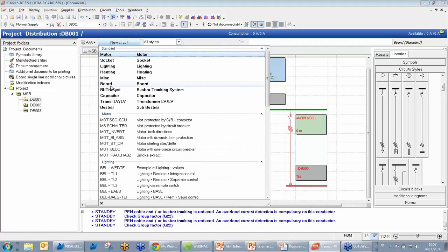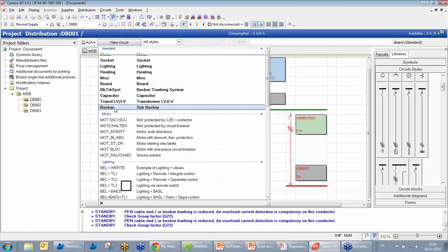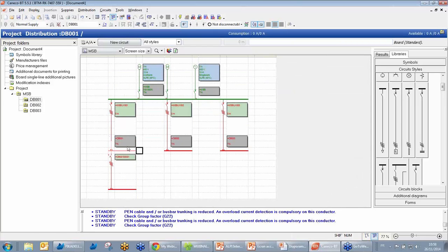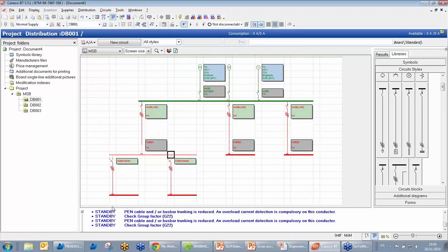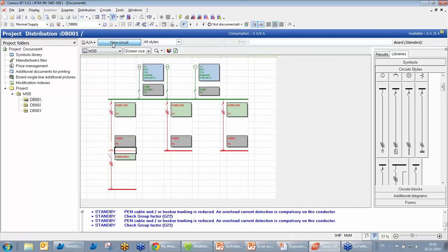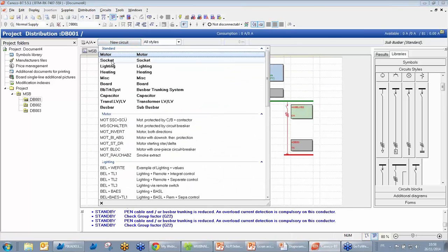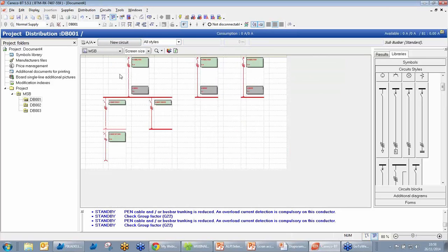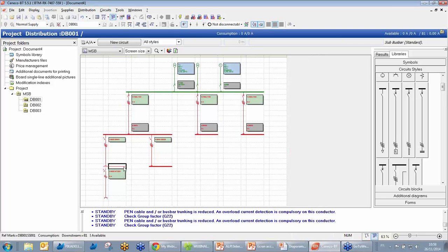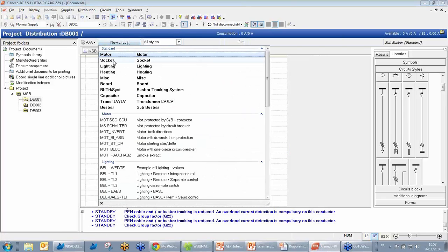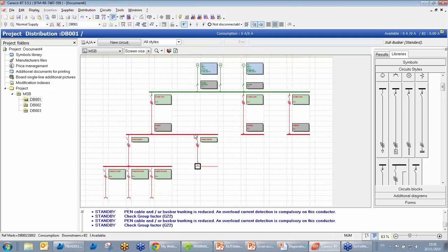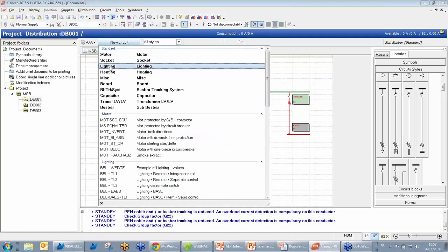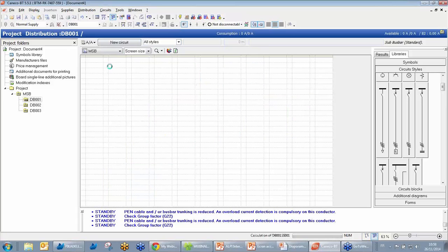Okay, then I can create some bus bar for the first one. Create another one. Create 2 bus bar. On the first one, I want something like for a building, an administrative building. I will create some sockets. Open 1, 3 here. I want some lighting circuits. 3 or so.